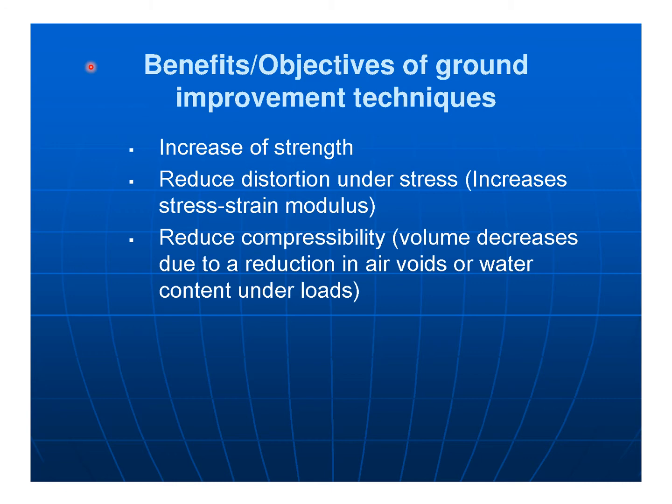Benefits or objectives of ground improvement techniques: increase of strength, and when we use the term strength it means the shear strength. Reduce distortion under stress, that means increases stress strain modulus. Reduce compressibility, that means volume decreases due to a reduction in air voids or water content under loads.